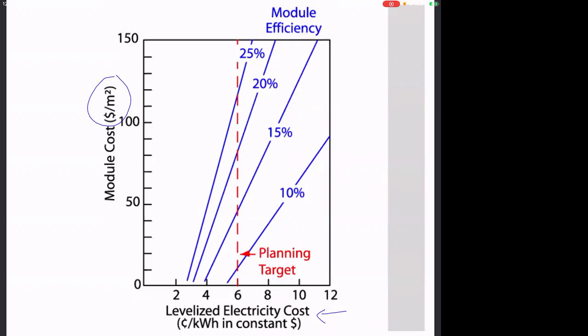So it's averaged over some utilization time, a year typically, or several years. The lifetime, typically it's the lifetime of the panel, which can be 30 to 50 years. So here you see various plots, and as the efficiency of the module increases, these plots become more vertical, which is great because that is saying that the module cost has a lower effect on the levelized cost of electricity, which is what you want, both as a consumer and also as someone who might be selling the modules,